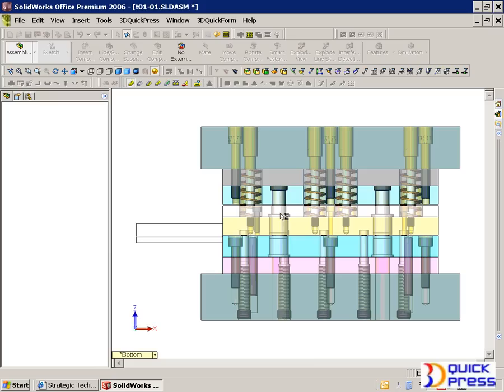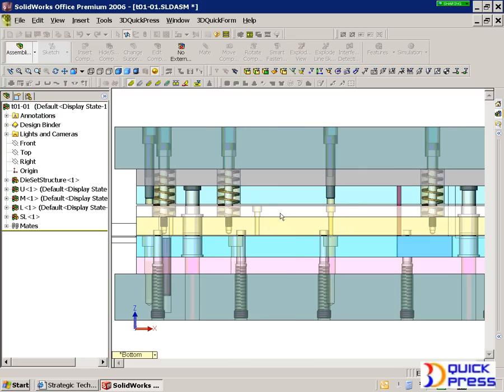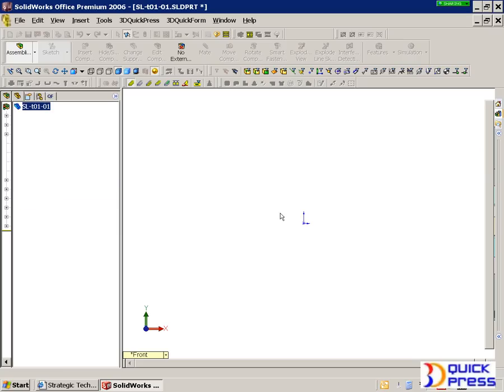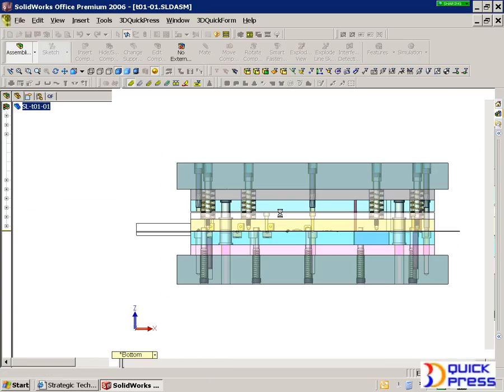So here we're going through, each assembly is being created, so now we have a final upper, middle, and lower. And of course the components are being transferred into the proper subassemblies. Also, everything's being renamed, so you don't have to sit there and mess around with all the different combinations of naming conventions for the current job. Of course, standard components don't have to be renamed. They could be called from a standard location, or they could be if you prefer that.